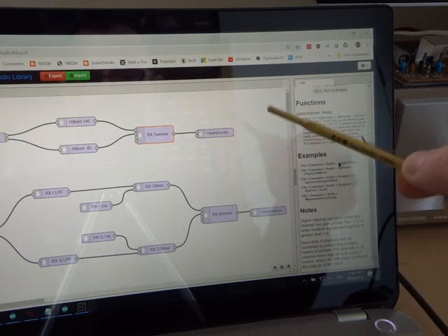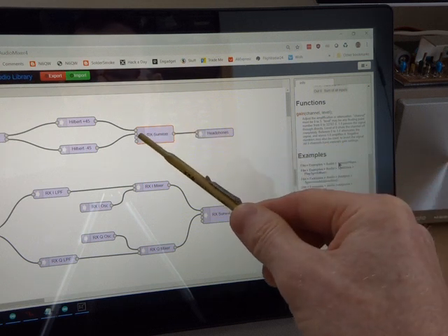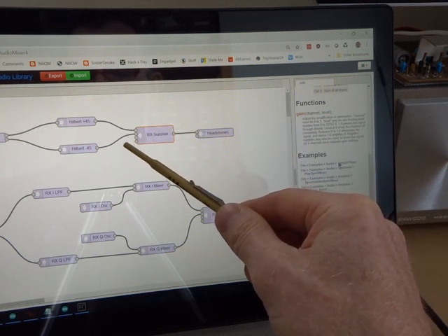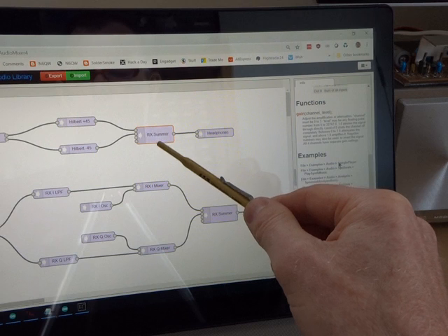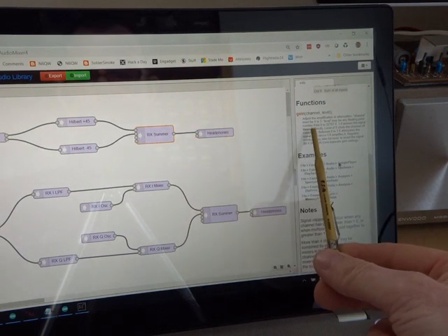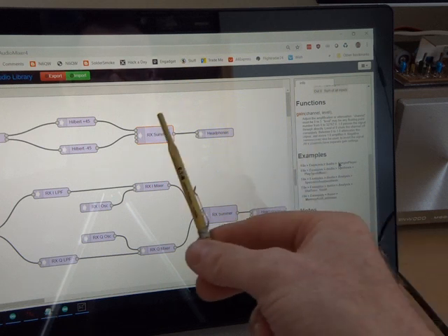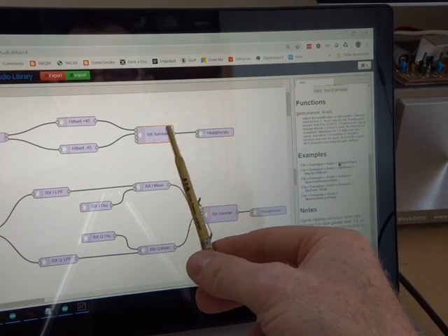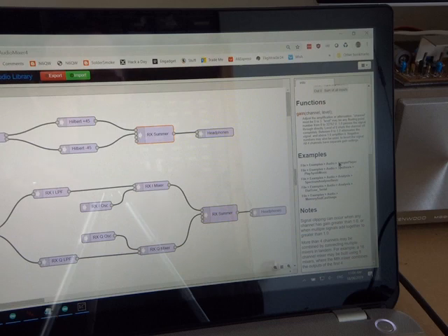So we've actually now inverted the input, and now if you were to sum that inverted input with the other input, you've got essentially subtraction. So that's the method, as you'll see in the code, for very easily converting that into either sum or difference to recover either the upper or the lower sideband.